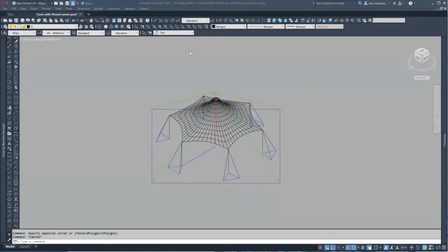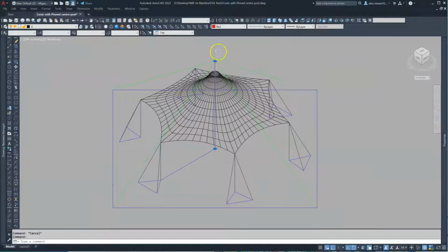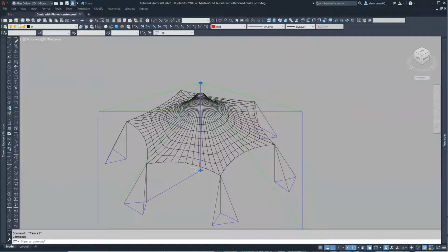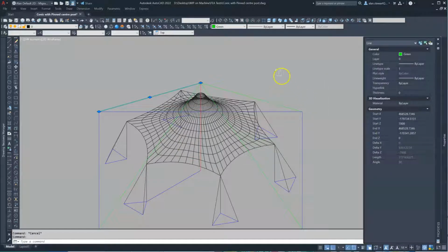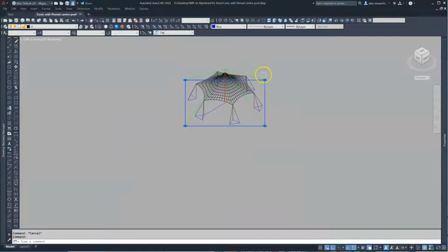In the second configuration, the center post has been raised a meter higher than the bail ring, and this remains a 3D polyline as before. We also have now 4 lines which I've assigned the color green to, and an additional 3D polyline that restrains the base of these guy lines.